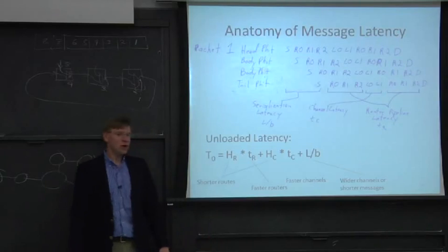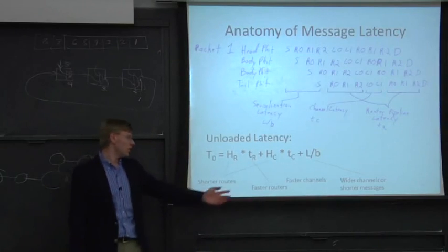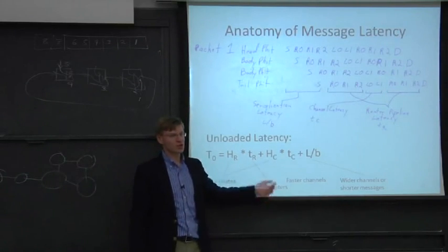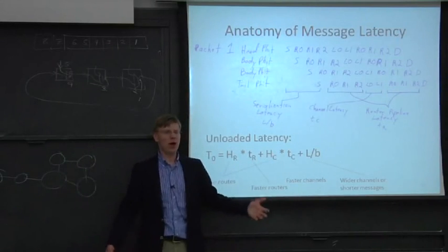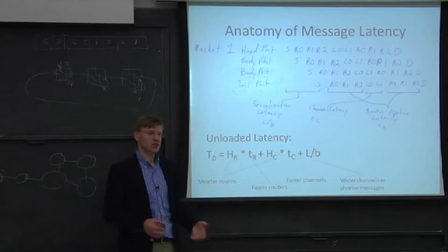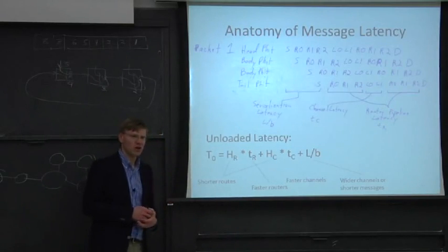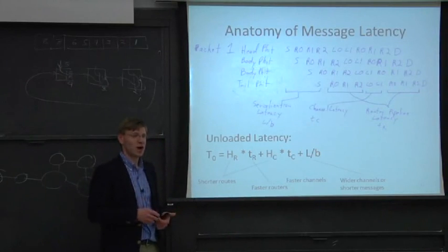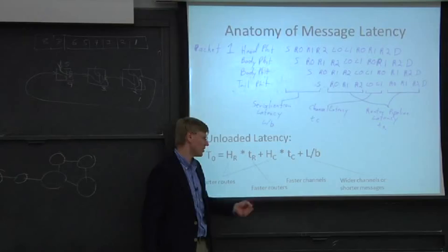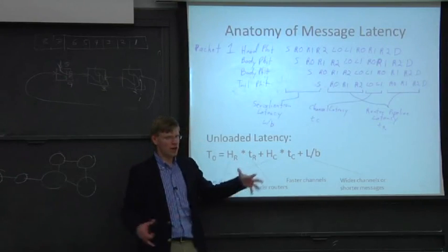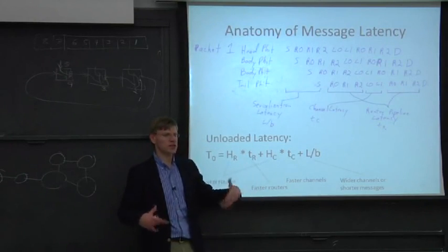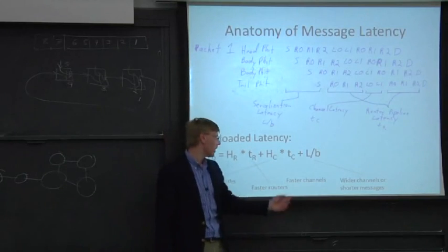You can make the routers faster. So you can either increase the clock frequency of the routers, or you can make them wider if they take multiple cycles. Now, if they're already sort of as fast as you can go, it may be hard. You might be able to increase the clock frequency somehow, but it could start to get hard at some point if they're already wide channels and wide muxes and have a fast clock rate.